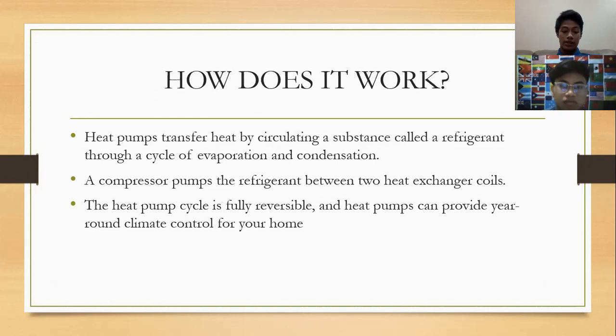And in cold weather, the outdoor unit of an air source heat pump needs to be intermittently defrosted. This will cause the auxiliary or emergency heating elements located in the air handler to be activated. At the same time, the frost on the outdoor coil will quickly be melted due to the warm refrigerant.